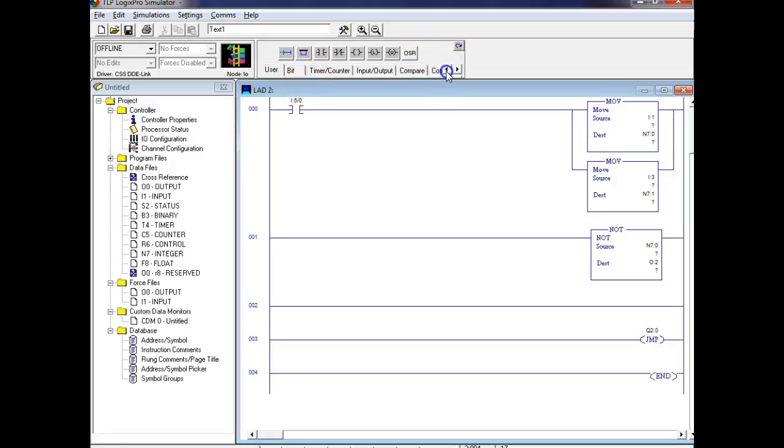Okay, guys, what's required for a jump instruction? But the label is considered to be what type of instruction? Input. And the jump is considered to be an output. So what do we need to put on the right over here? So it labeled this Q2. So Q2 is the file we use for our jump instruction. Not O, Q2. So it automatically stuck that in there for me.